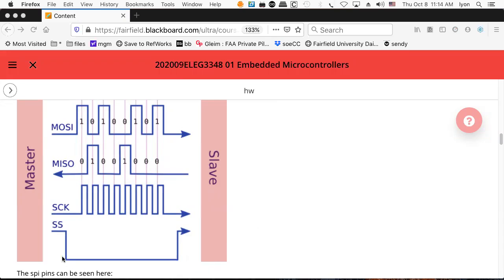The basic limit, of course, is that you've got to select every single device. So your master will always be the CPU and the slave will always be some device, and you can't go faster than the device can take. So that's a basic fundamental limit. That's the serial clock input for your device. And you can find out what the limits are.